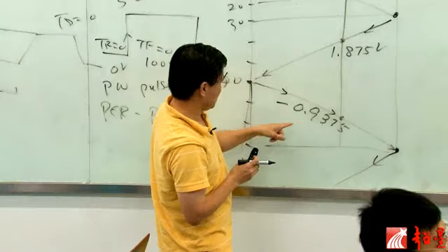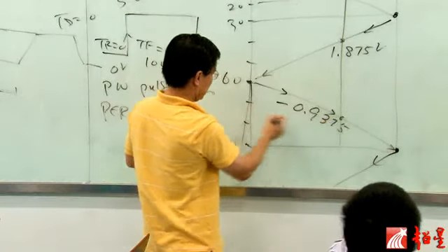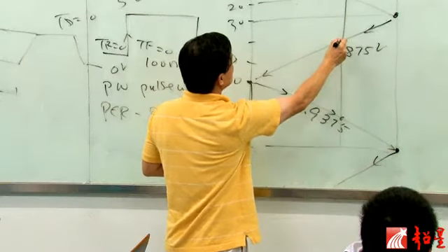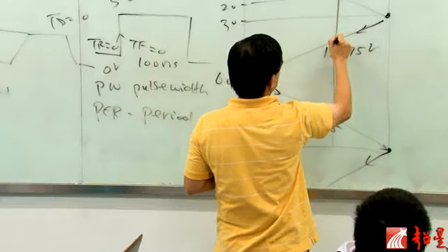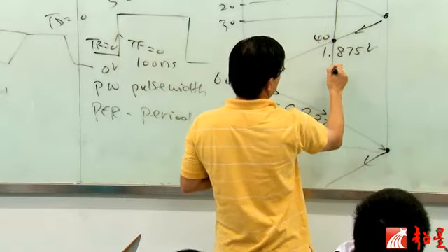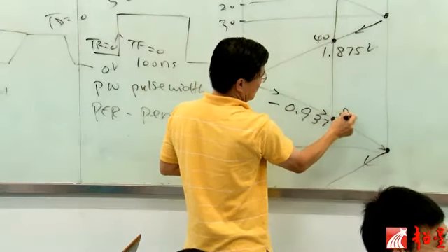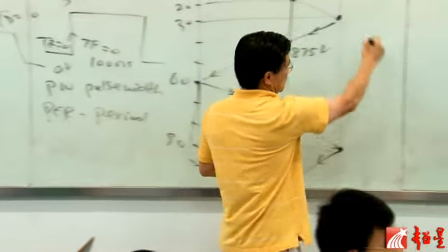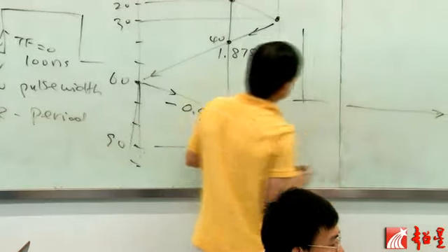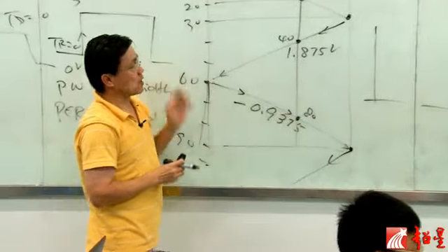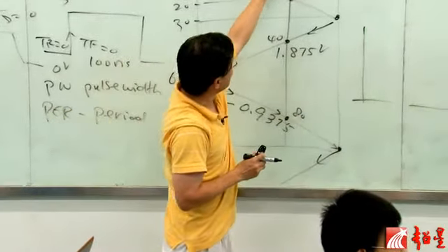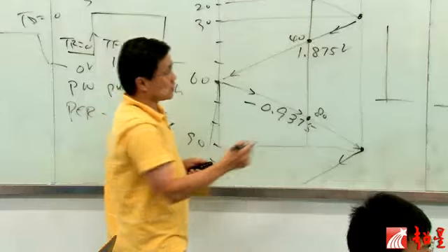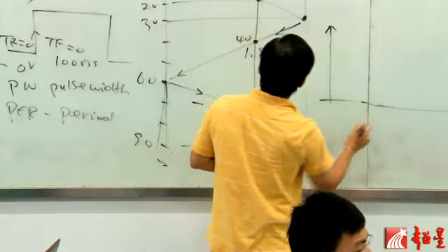And then at, what is this point? 80? Oh, okay, so this is 20, 40, and it must be 80 point, right? Yeah. So draw the timing diagram. As you can see, it's very easy once you have a bounce diagram. You basically just draw a vertical line here, and then just add the voltages correctly at the right time.